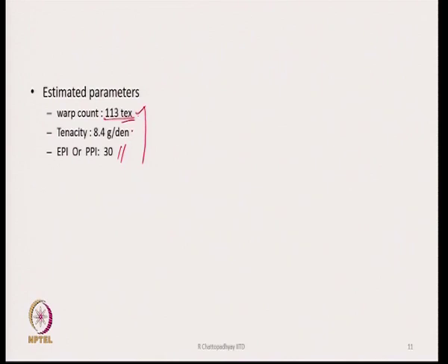So, whatever is available closest to these values, we have to choose that yarn from our inventory and then recalculate whether, if I use the yarn which is available, which is closer to this, it will meet the requirement of strength in both directions, warp and weft, and whether it is going to meet the GSM requirement and the thickness requirement or not. Okay.